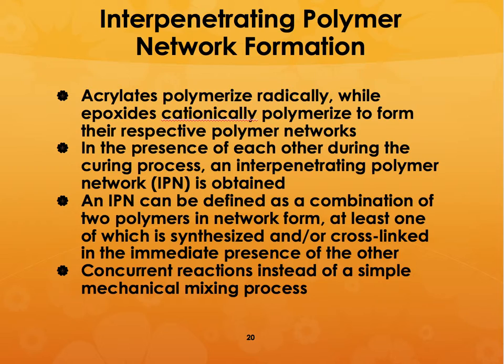Now, as I said to you, one of the reasons why acrylates result in a considerable amount of residual stresses is because they polymerize pretty rapidly, and they would polymerize to form their respective polymer networks in the presence of each other during the curing process.